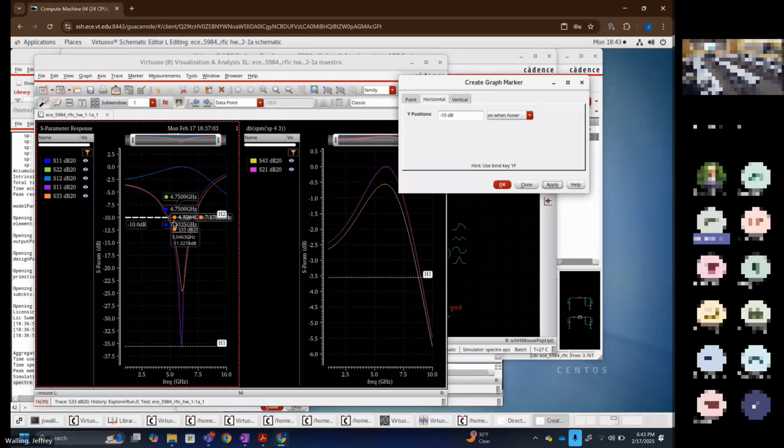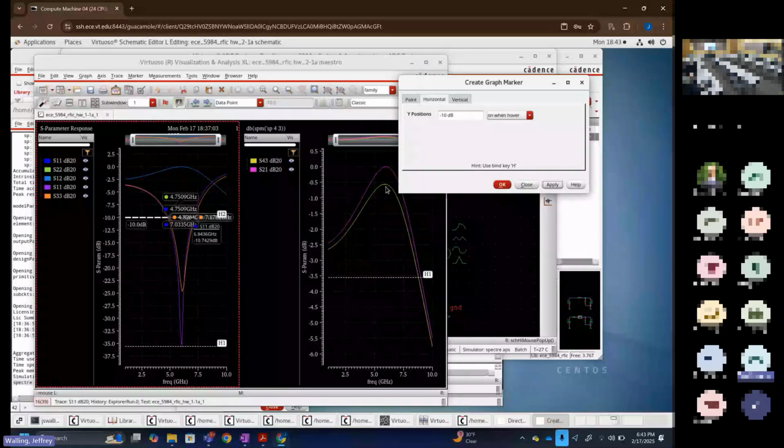Sorry, I was just wondering if you could repeat what you said about crossing at 0, because I'm seeing how we estimate the Q. It's the frequency at the high and the frequency at low. So if we substitute 0 for one of those, wouldn't that make the Q 0? No, it's FH. It's the crossing point at the high frequency minus the crossing point at the low frequency divided by the center frequency. So it won't be 0. Okay. Thank you.